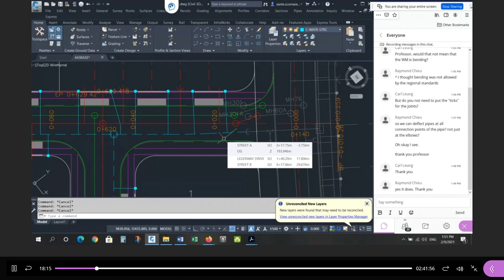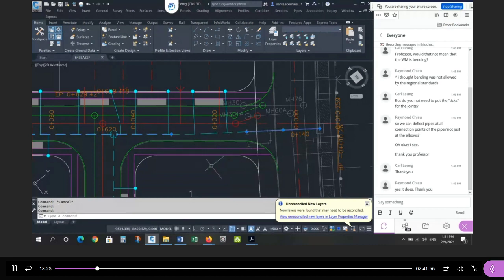Even the smallest bend, 11 and a quarter, is going to bend the pipe too much, and you're going to miss connecting. Okay, so the best solution here is to fillet between the standard position and the existing position with a radius of at least 170. That's why I used 200, and we were able to achieve that. And again, I drew a radius. I didn't draw the kinked pipes with the 3 degrees or the 2 degrees bends, right?